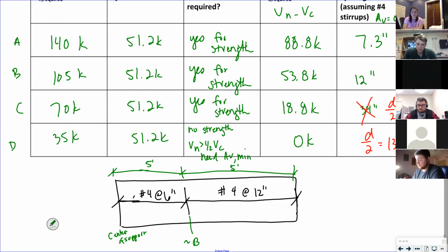We're not out there with a measuring tape making sure it's exactly 6.2 inches apart or something like that. We need 30 of them over here for over 5 feet and 10 of them over here over 5 feet, something like that. I'm not doing the math yet. Yeah, and I think our guys have like a tolerance of plus or minus a bar diameter. Yeah, so it's going to be off anyway. So really, it's 5 feet.